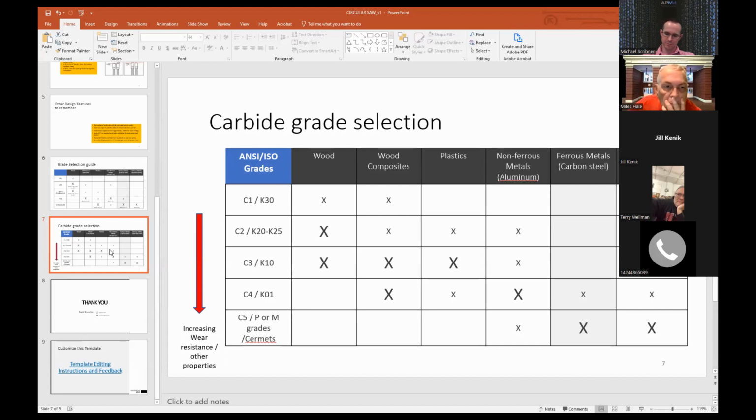And then when you get down to really the metal cutting grades, P or M is what you'll see for most of those, and/or Cermet, which is ceramic metallic grades of a cutting form now, not carbide, but ceramics, which is really the newest kind of tooth form you'll see out there, again, for cutting metal. Several manufacturers in the last few years have come out with blades, along even with my current employer.